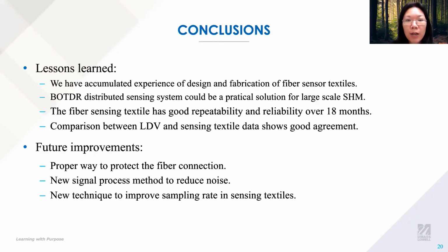So through this project, we have learned how to design different patterns on the sensing textile and also how to fabricate and manufacture the fiber sensing textile with Xingwei. We also learned that the BOTDR could be a practical solution to monitor large-scale structures, as we said that BOTDR could collect data for up to 80 kilometers long. The fiber sensing textile provided a reliable signal over 18 months. The data compared between the LDV and sensing textile shows good agreement.